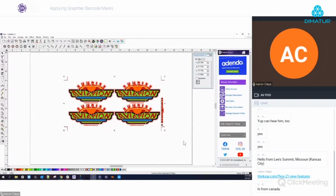But now Flexi 21 has the ability to do this right inside of rip and print, which is where normally you would apply most of your contour cuts and your registration marks inside your job. So let's go ahead and clear all this off. So we're going to get rid of the marks here. And this is where we're going to spend the majority of our time. So we're going to clear off this contour cut mark because we don't need it. We're going to leave the contour cut on there. And then we're going to go to rip and print.